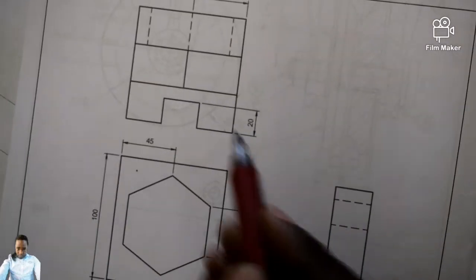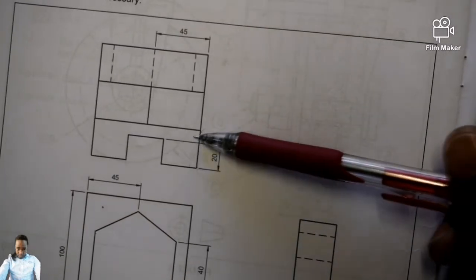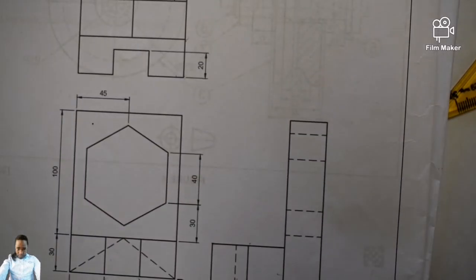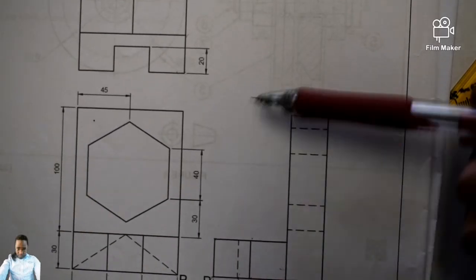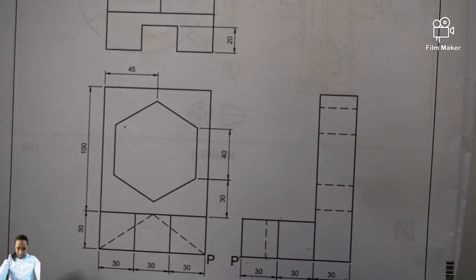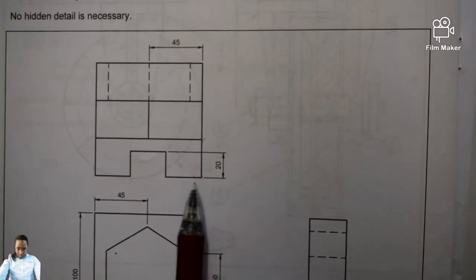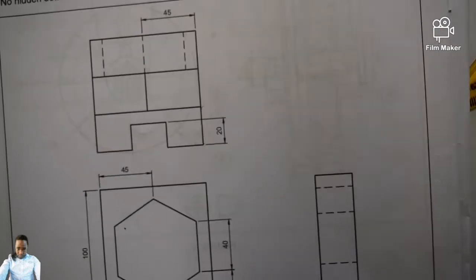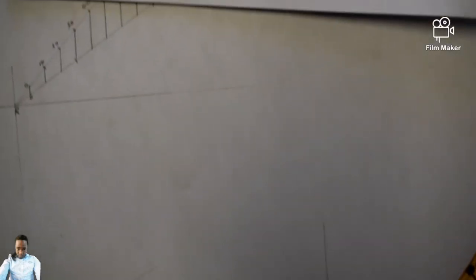They told you what is 20 millimeter, because the right view as well as the top view, they will always share the same width. The front view as well as the right view, they will always share the same height, and the top view as well as the front view, they will always share the same length. All together. So from here till there is actually being dimensioned for you there by your top view, which means it's 20 millimeter.